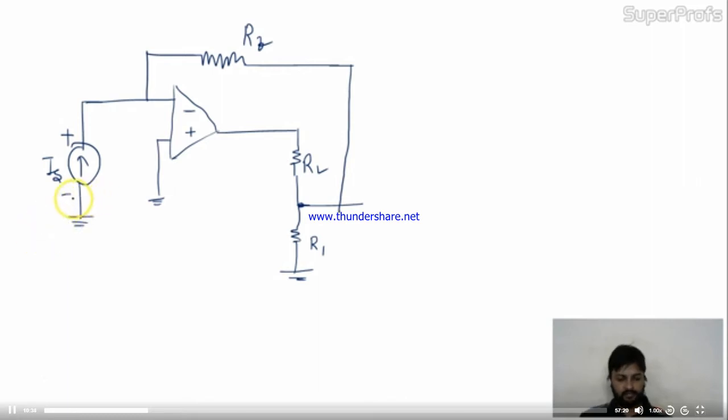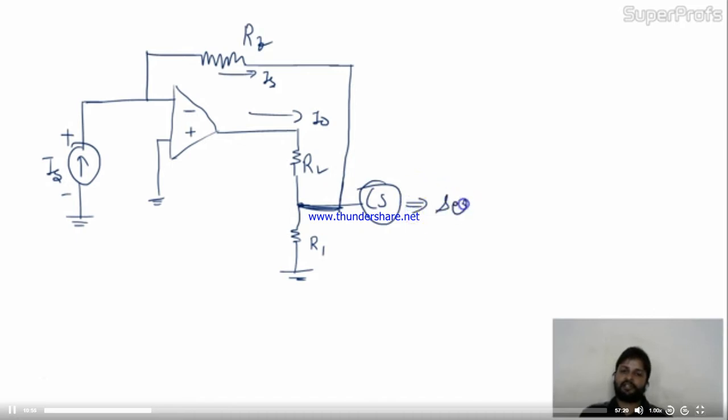It's like this. Now we have to identify which type of topology it is. Okay. So see, if this is the feedback current, now after the load we are taking it. After the load you are taking means this is a current source. Current source at the output stage is series. So at the output stage it's a series combination.